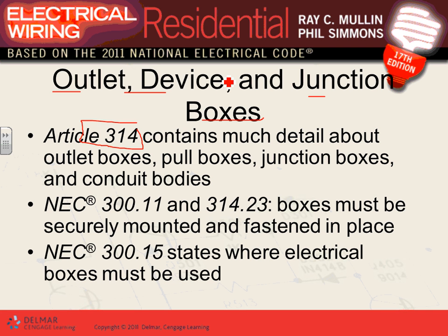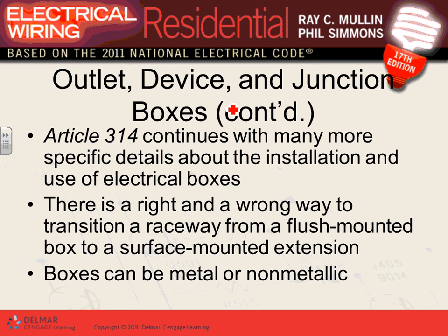So if you're electricians, you find some of them splicing and throwing it right behind the sheetrock wall, like they do sometimes, when the inspector is not there. Unacceptable, it must be in a box. And the boxes have to be securely mounted to wherever you put them. They can't be loose up in the air. They have to be securely mounted to a wall, ceiling, floor, whatever. And these are requirements from 300.5 state. Electrical boxes must be used and they must be secured. So that will give you why we use them.